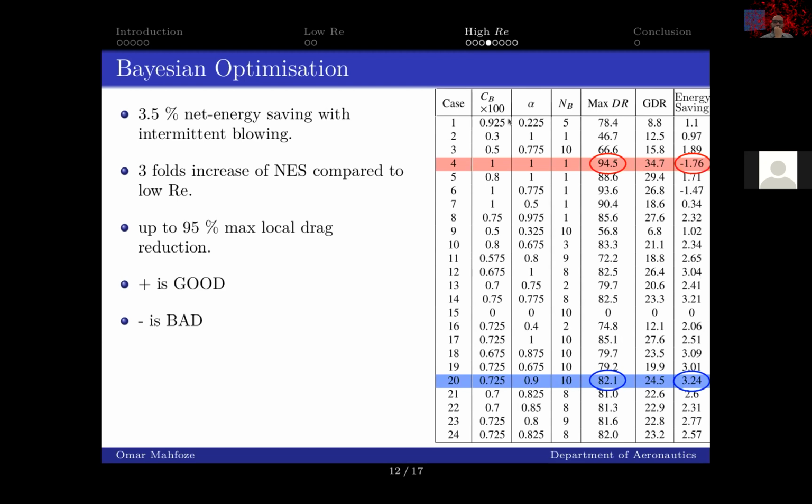On the other hand, if we apply uniform blowing with intensity of 1%, then we can reduce the drag by 95%. And in that case, we are going to pay extra energy as low as 2%. And this is a very interesting situation in case someone wants to increase the speed of a vehicle or an aircraft without paying much, for example, without using an afterburner in a jet fighter, then you can use wall blowing to reduce the whole drag.